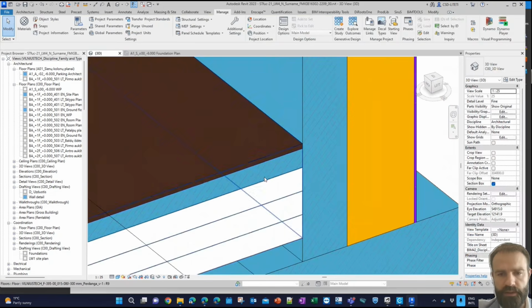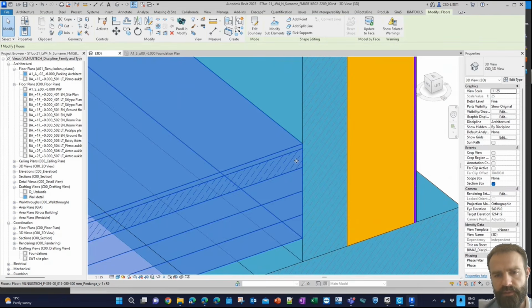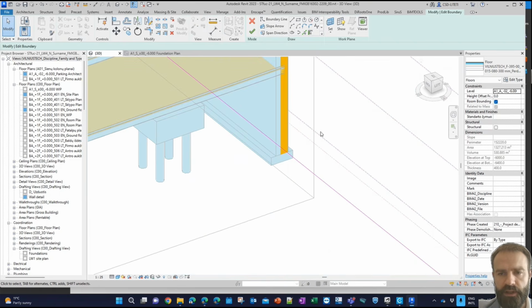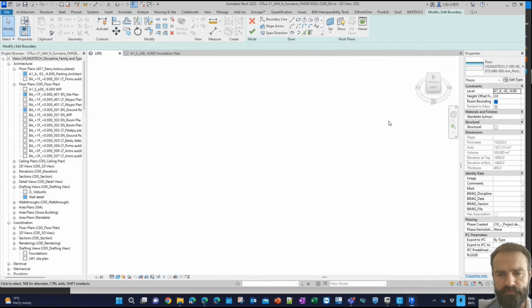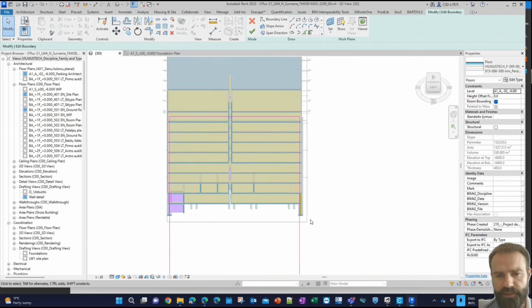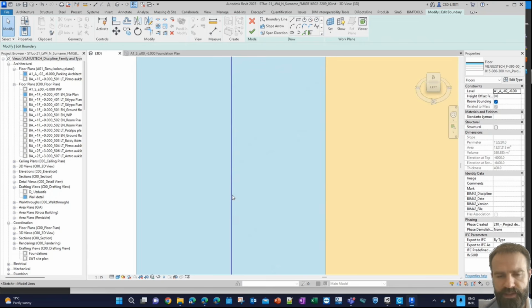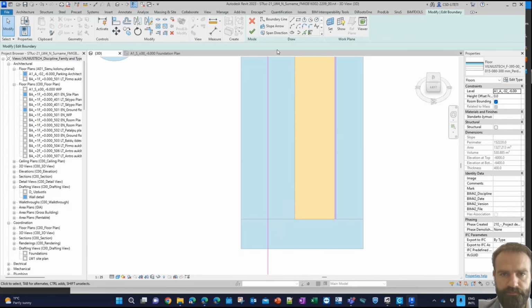So now regarding the ground floors. Ground floors should end to the side of the car parking wall. So it should be by the side. So it means if I double tap and look from the plan view, the line should end to the side of the bearing wall.